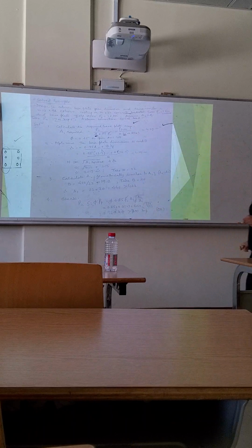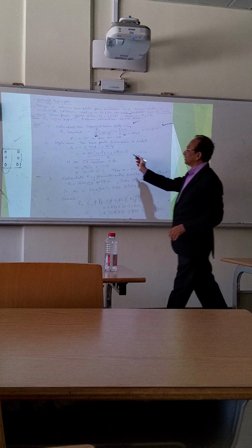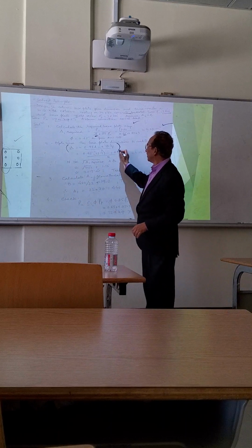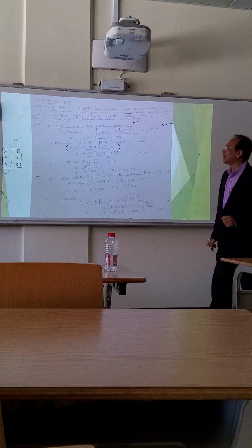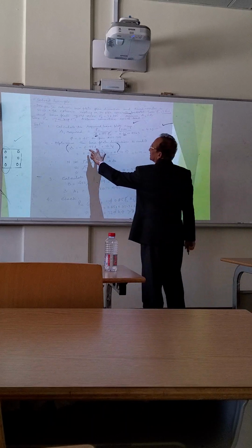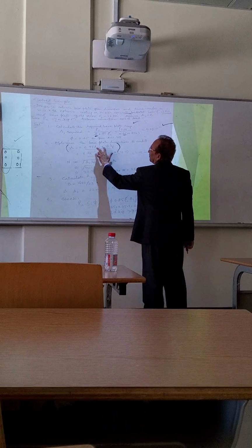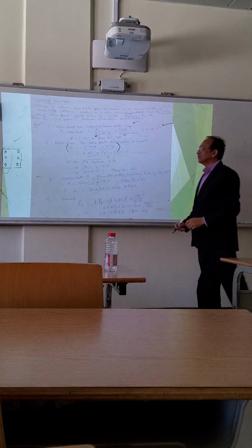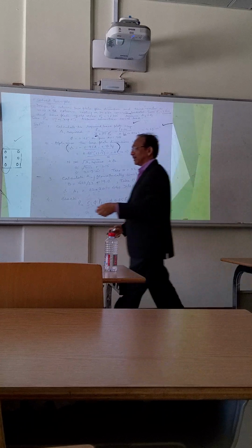Now optimize the base plate dimensions N and B. This is something different from the previous question. You have to find this number delta, which is 0.95D minus 0.8 BF, divided by 2. How are you getting this?